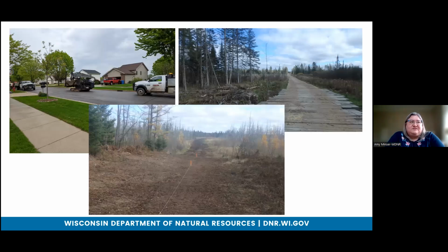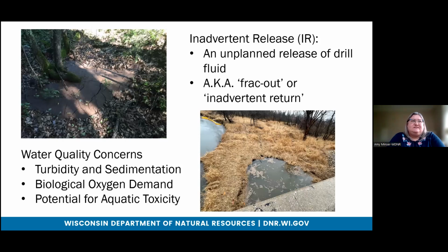So these are pictures of what we like to think that the drill path is going to look like. And a lot of times it does, but occasionally you have what's called an inadvertent release, or IR, which is also known as a frac-out or an inadvertent return. And it's just an unplanned release of drill fluid.